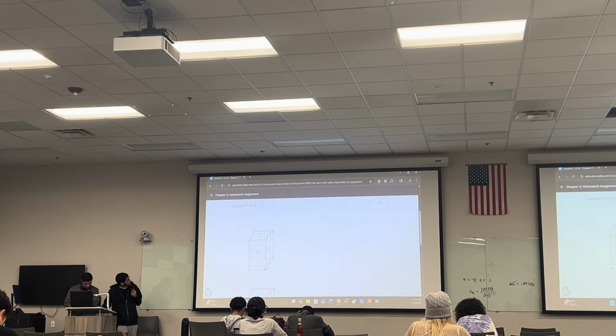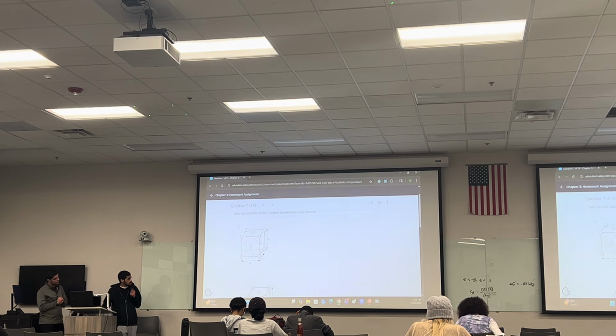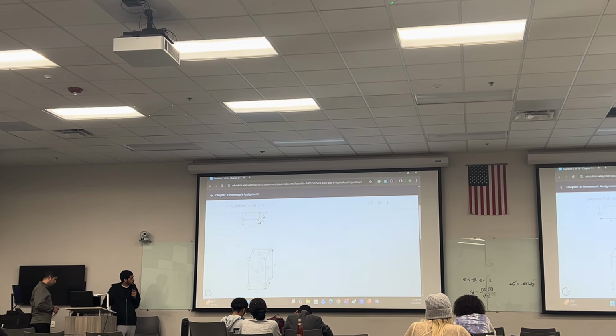You can see that you have atoms here in the face, and all your atoms at the edge. But it's taller, it has a height C to it, versus the cubic FCC, which only has A on each side, which means that it has equal unit cell length on each side. So this would be the one that you would select because that's the orthorhombic FCC structure.